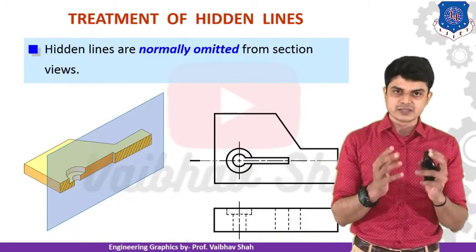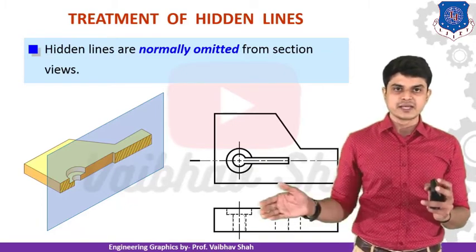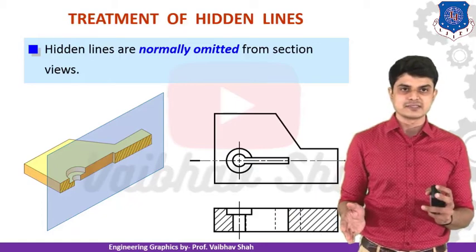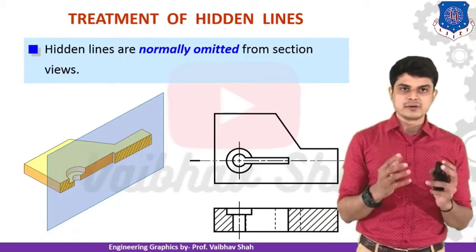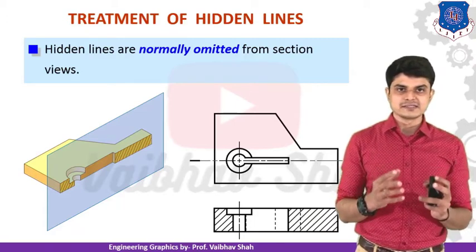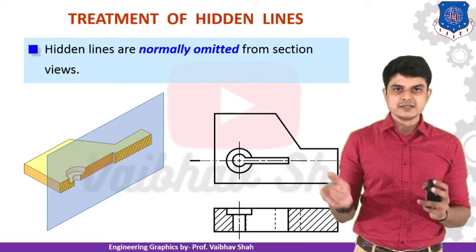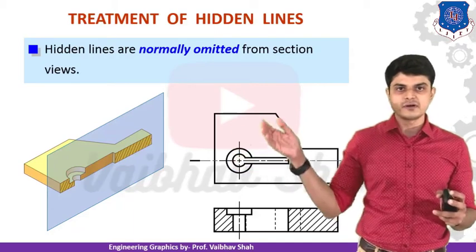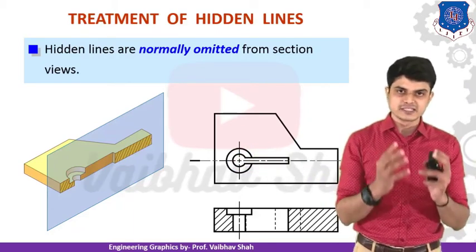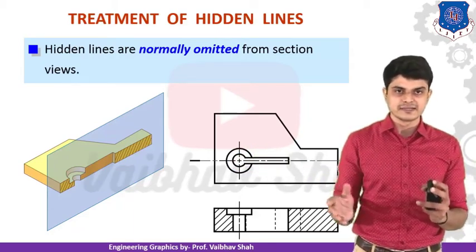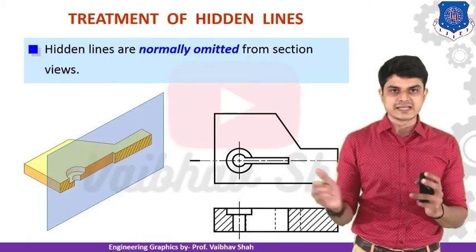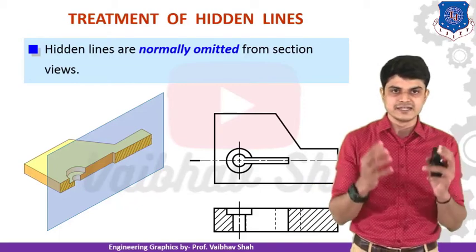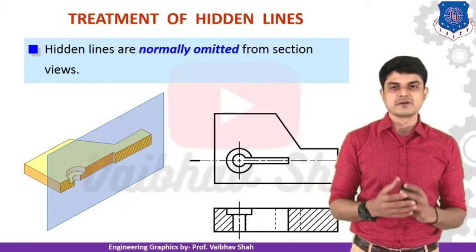When we are cutting the object, we will be converting this dotted line into full lines, as you can see, and we are showing the remaining portion by this hatching line. But remember, a certain portion of the lines is still hidden behind this part. You can see there are certain portions of the object which are still hidden behind this part, which should be shown by the dotted line. You need not draw each of the parts of your solid by a hatching line, because certain lines are hidden on the back side of your object.